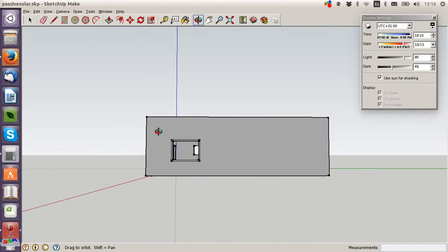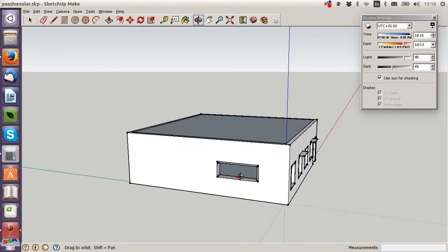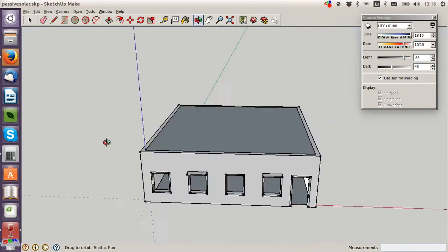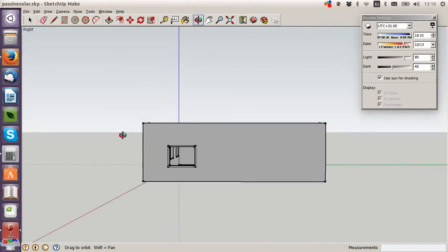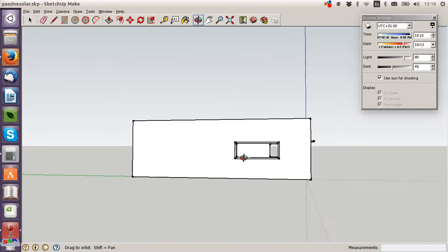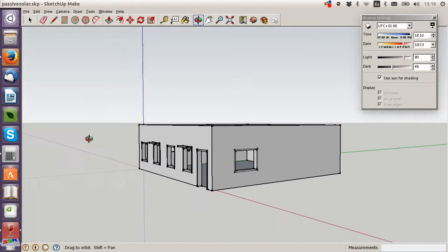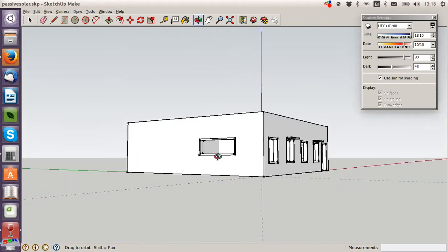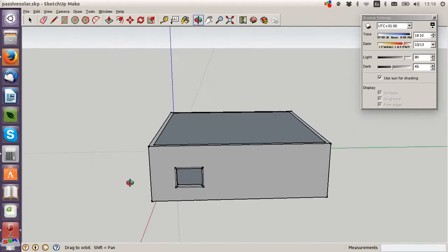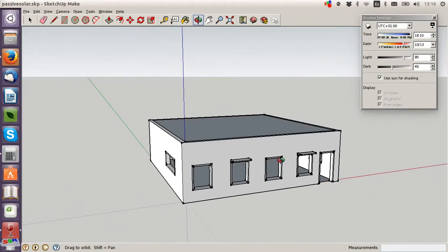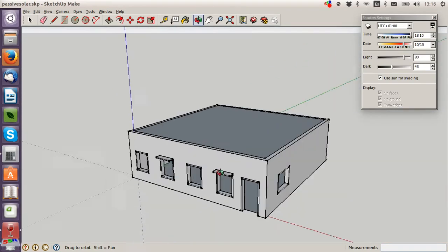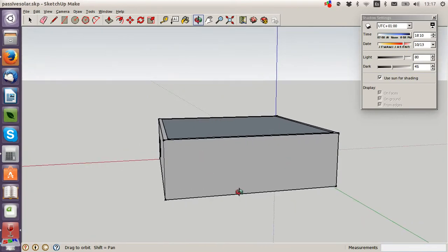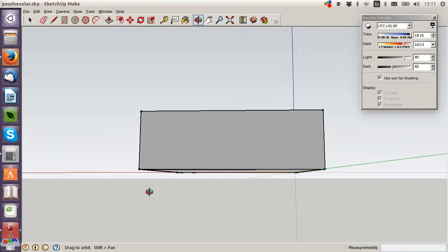Minimize the windows on the east and west faces, even though obviously you can put shutters on those and close them in the summer. It's quite nice, I suppose. In the winter we have a similar setup to this, where we have small windows on the east and west, and we'll just keep them closed in the summer. So minimize the glazing on east and west faces, and if possible put no glazing on the north side.